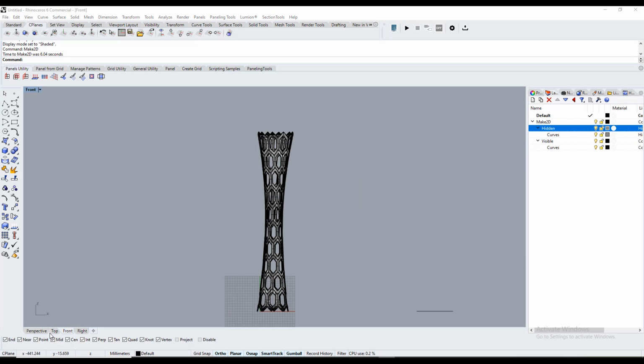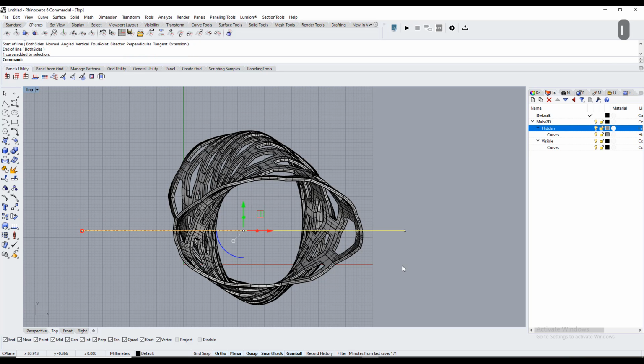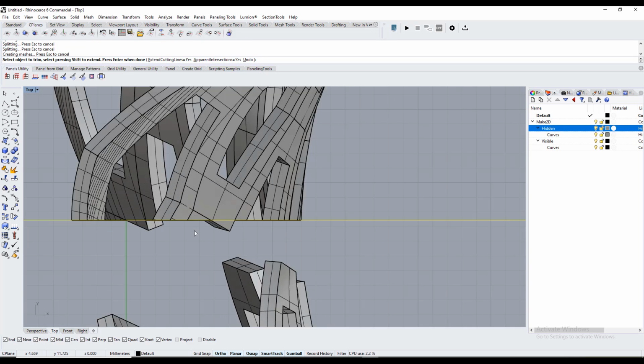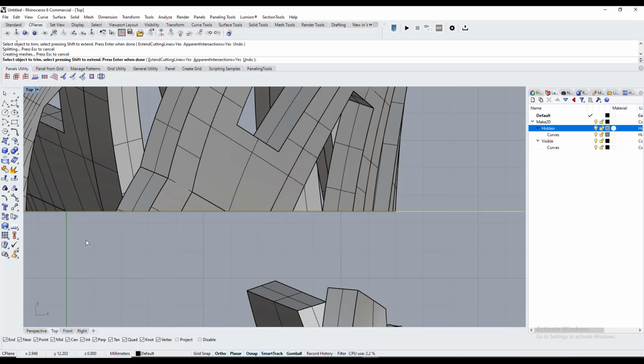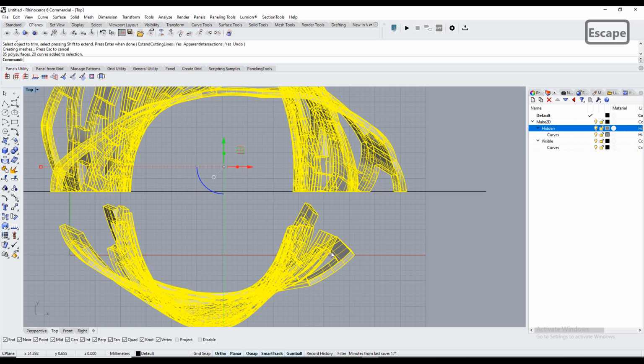Similarly, we can make sections as well. In order to do sections, we just have to go to top view, draw a section line, trim the side that we don't want, and wait for it. It may take a while from time to time. It may take several trimming attempts to create a perfect trim, and then ungroup it, as we have done previously with flow along surface.